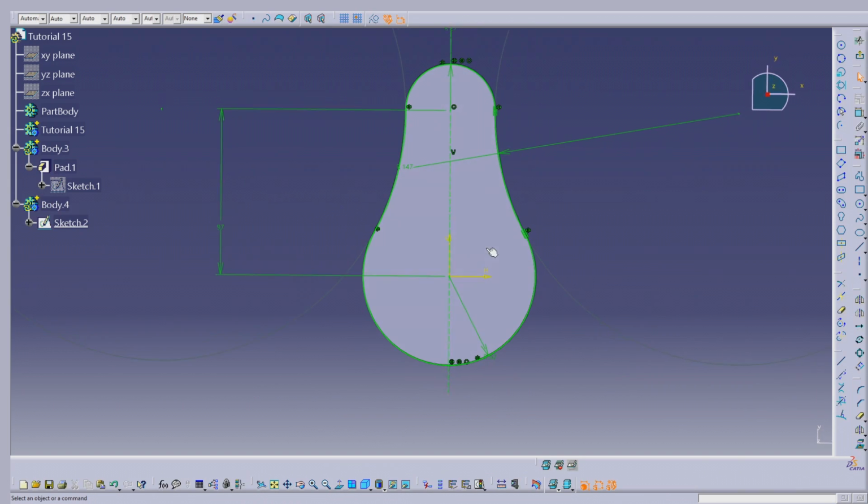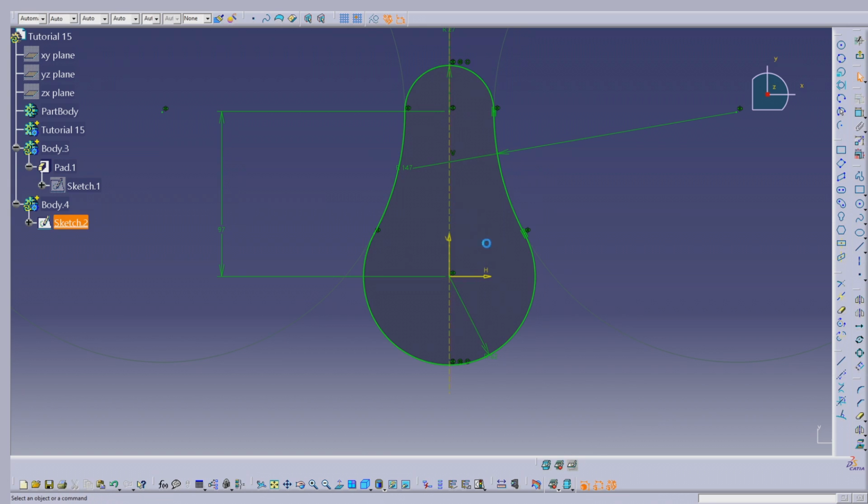We're gonna go inside of the sketcher, click this option to not be able to select the background constructions, and click on every one of our constructions, and make it pointed, as the line that we did on the vertical axis, in order for us to have a guidance.